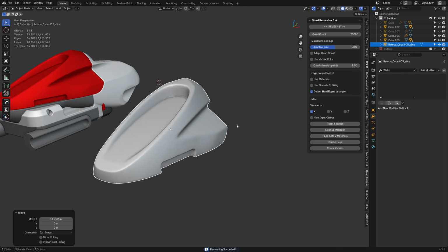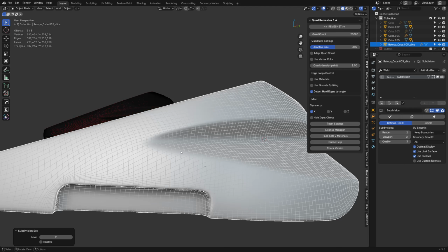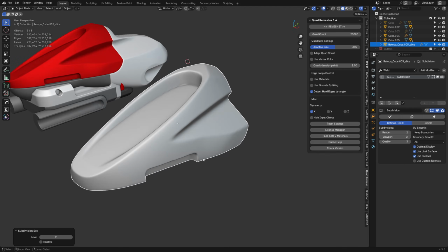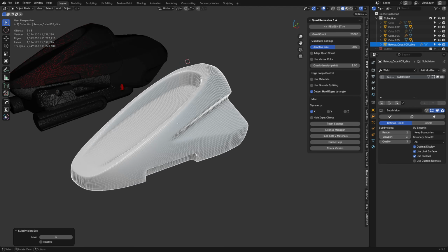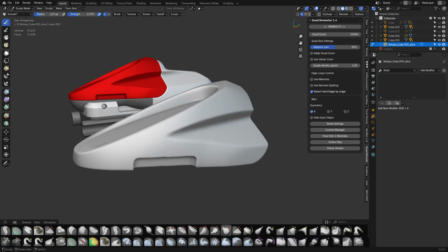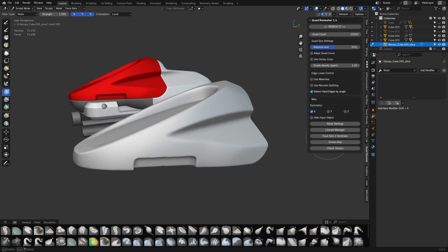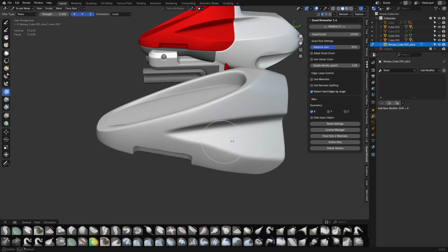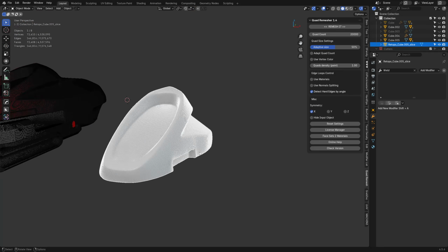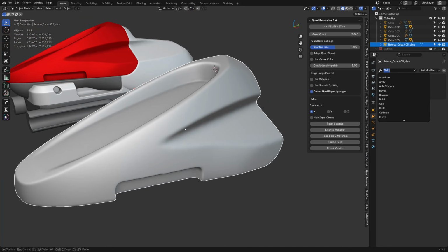So that means manual retopo usually. See? It starts to look a little bit more questionable, perhaps. Well, one thing you can do with it that's kind of cool, though, is you can remesh this pretty high if you wanted to, maybe once or twice or so. Go to sculpt mode, mesh filter. You can also do a big relax across the whole surface. Sometimes this helps it out a little bit, makes it look a little bit nicer, perhaps, as far as those edges go. Not always, but you do this once, subdivide it a couple times, and you've got a dense mesh again. You can also try smoothing it.